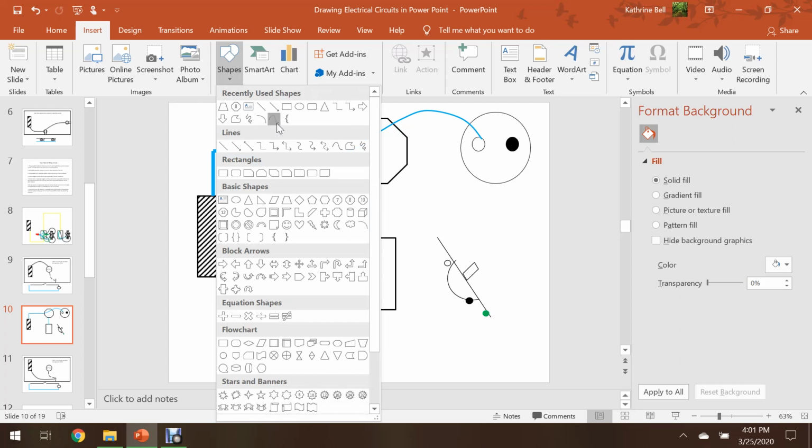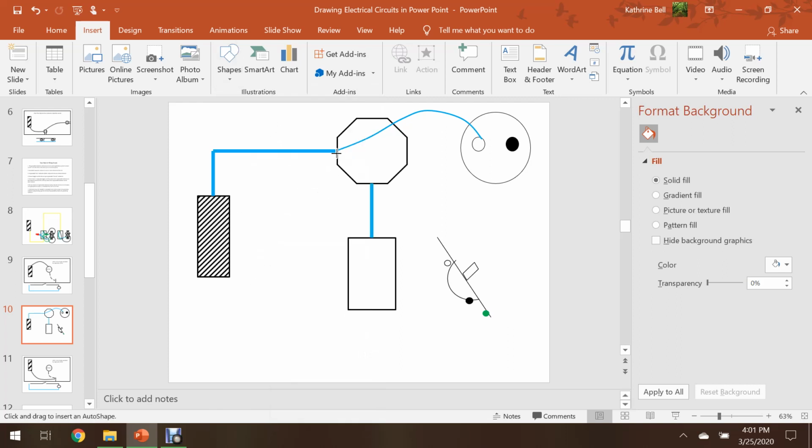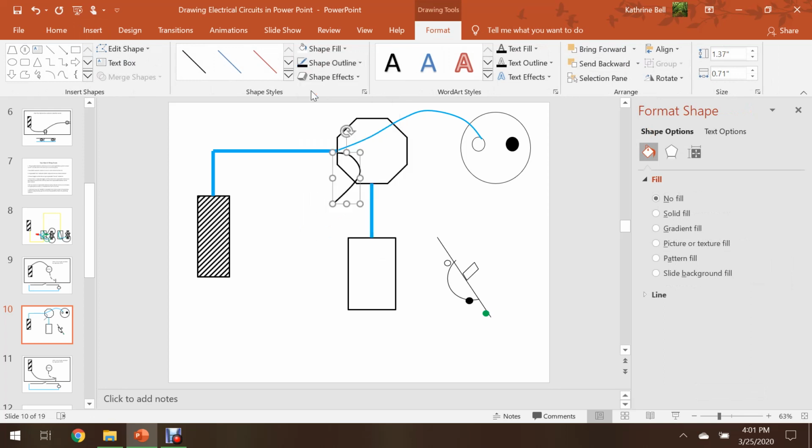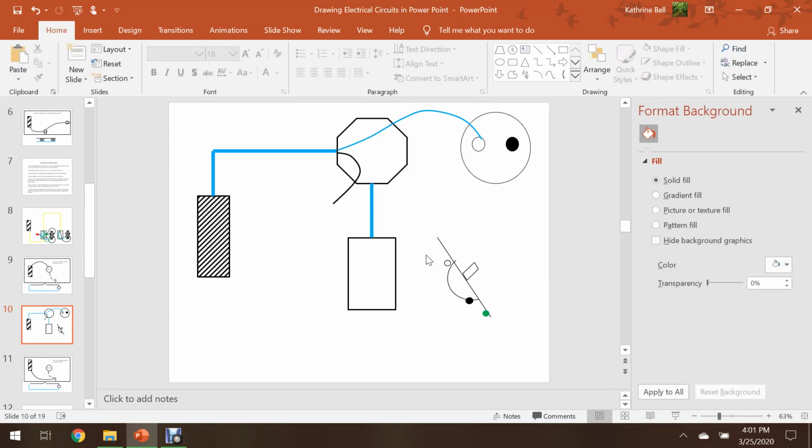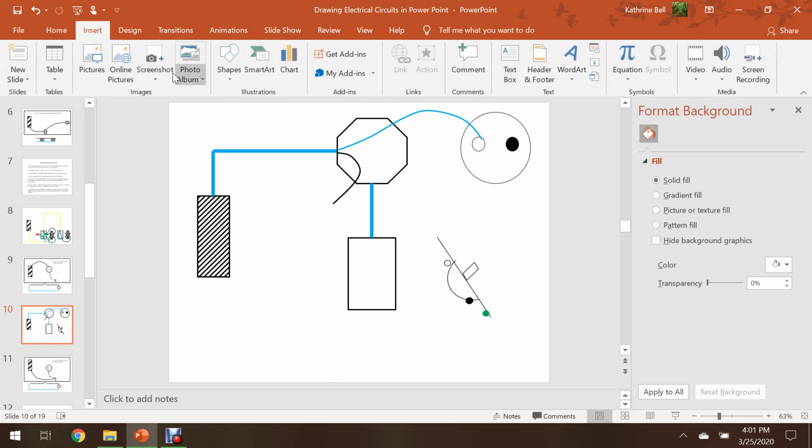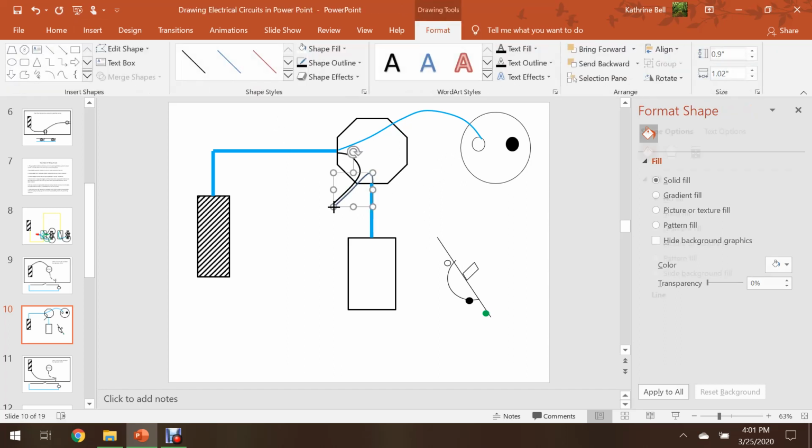So let's come in here now and let's draw our black insulated ungrounded conductor from our source. I want to change that to black. I've got to get power down to my switch. National Electrical Code 200.7(C) states that the white insulated conductor may be used to carry power to a switch, but that it cannot be used as the return from the switch to the light. So in this case, I'm going to draw in my white insulated conductor.